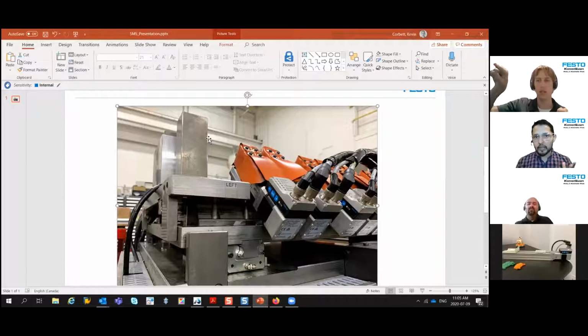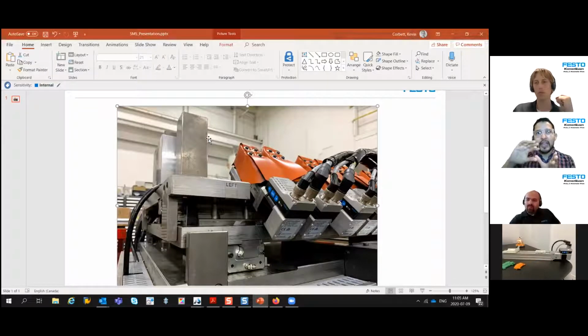Right, and this is the expected behavior. In this case, when you say position transmitter, you're talking about a sensor that's mounted on a pneumatic cylinder, and this sensor is detecting the magnet inside of the piston. Exactly. It's using the piston magnet to determine what position the piston is at.